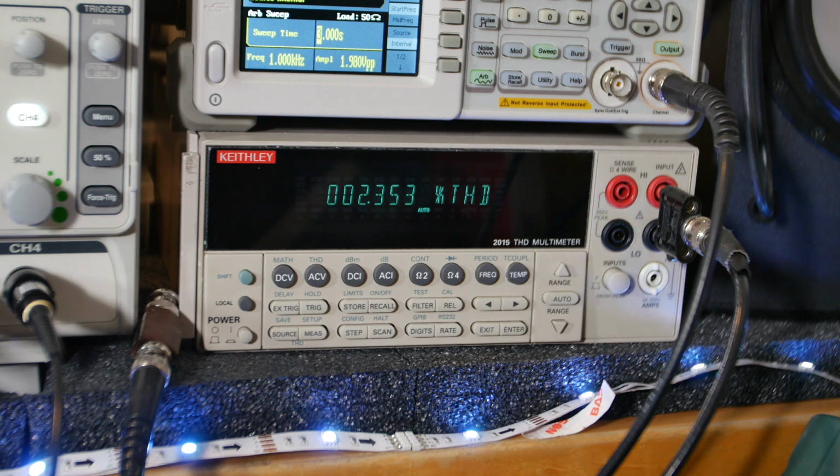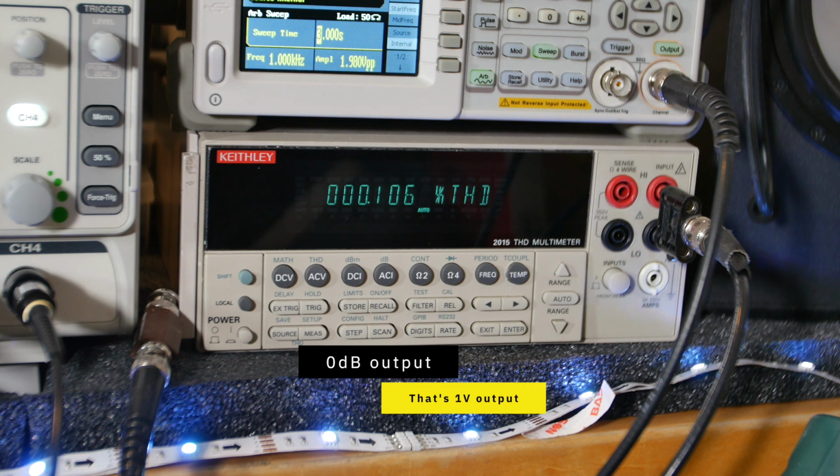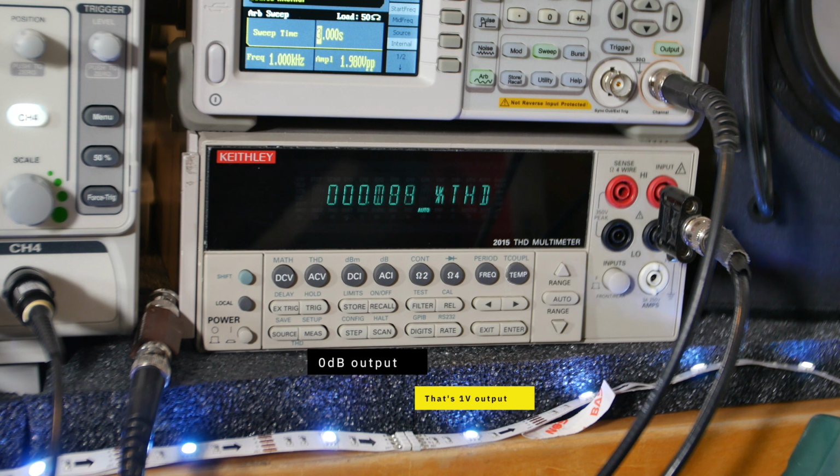So comparing the noise to that signal, it's about 2%. Now watch, I'll start bringing the signal up, and you'll see that percentage just drop. Okay, now I'm at 0 dB right there. So I got about 0.1 total harmonic distortion, and that's with noise and everything.